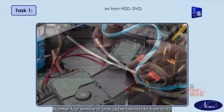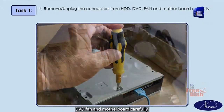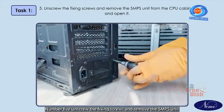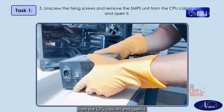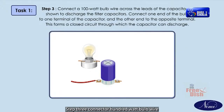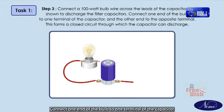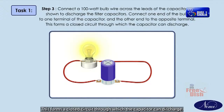Number 4. Remove or unplug the connectors from the HDD, DVD, fan and motherboard carefully. Number 5. Unscrew the fixing screws, remove the SMPS unit from the CPU cabinet and open it. Step 3. Connect a 100 watt bulb wire across the leads of the capacitor as shown to discharge the filter capacitors. Connect one end of the bulb to one terminal of the capacitor and the other end to the opposite terminal. This forms a closed circuit through which the capacitor can discharge.